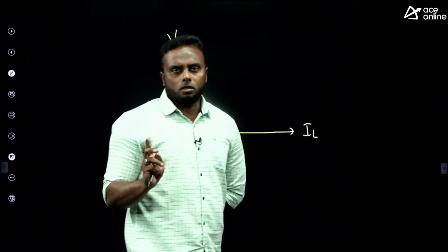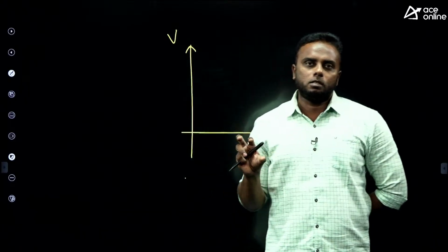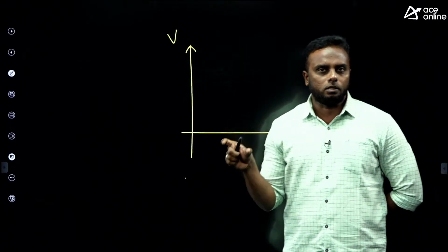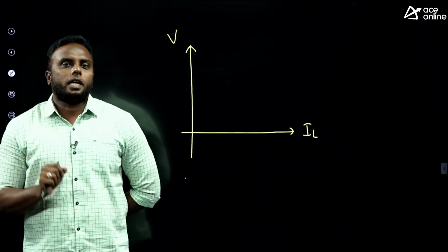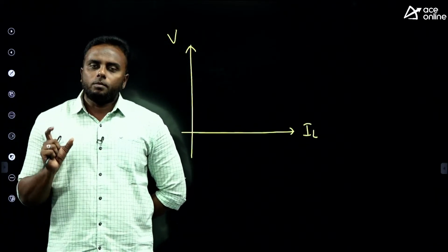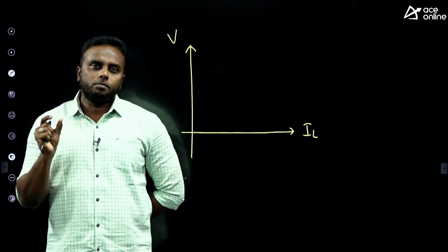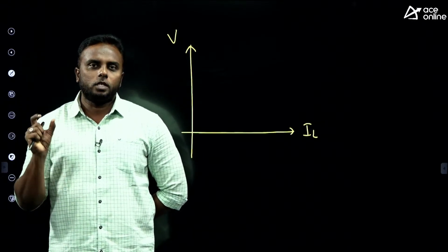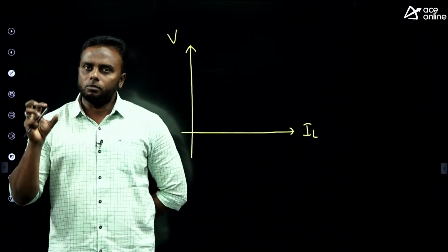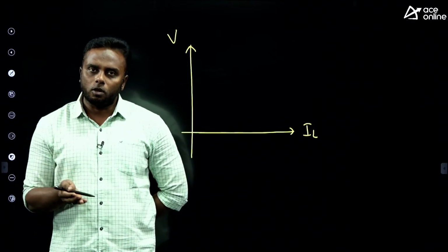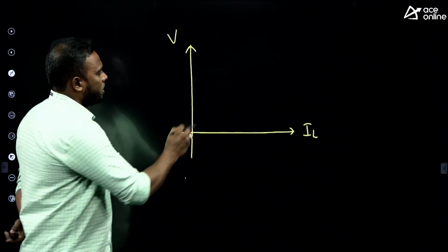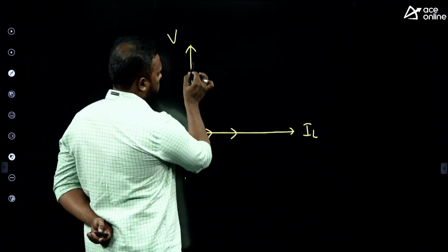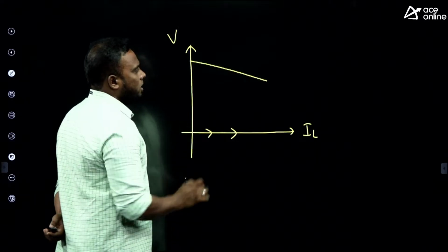One is resistance drop, which every generator has due to the resistance of the winding. Another is armature reaction drop. One effect of armature reaction is the demagnetizing effect, so some flux reduces and voltage drops.